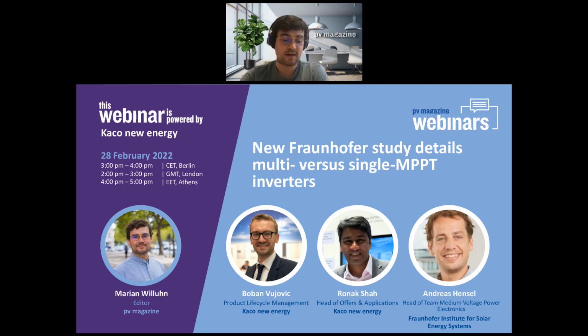These devices can optimize energy yield for any given environmental condition, especially since temperature and irradiation intensity alter the voltage and current levels coming out of the semiconductor. For example, the voltage of a PV module goes up as the temperature drops. A high number of such trackers in theory promises higher yields because there's a higher granularity of optimization. In practice, it might all look a little bit different.